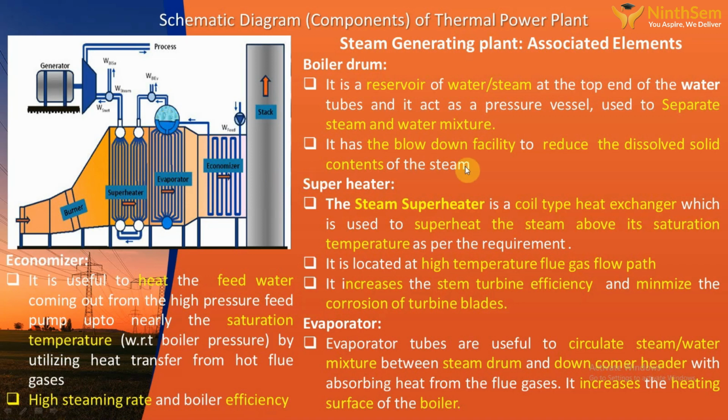The next one is that it has a blow down facility to reduce the dissolved solid content of the steam. When operating for a long time, sediments deposit at the bottom of the boiler drum.